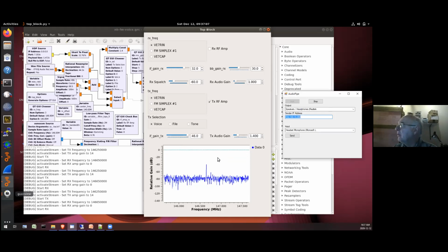So I'm going to push to talk. I'm going to send my call sign. What I want you to do is to watch three things at once. Over here in the debug message side, you're going to see the message that goes to the HackRF microcomputer saying switch to TX mode. So the last thing that happened was start RX. There'll be something that will say set transmit frequency to something else, set receive amp gain, transmit amp gain to on, start TX.